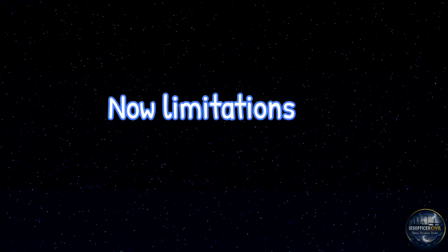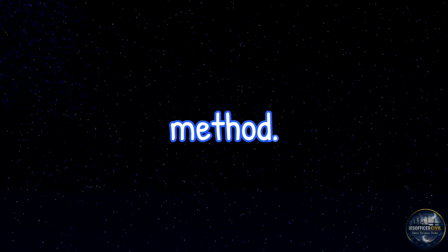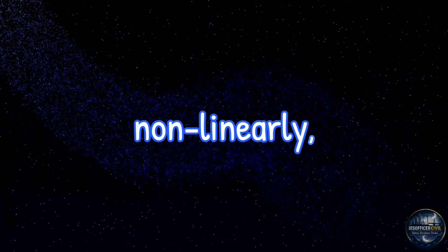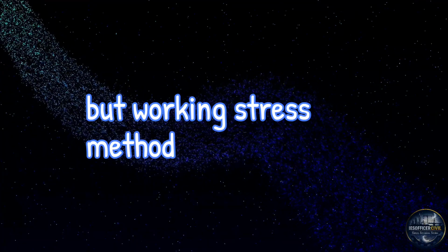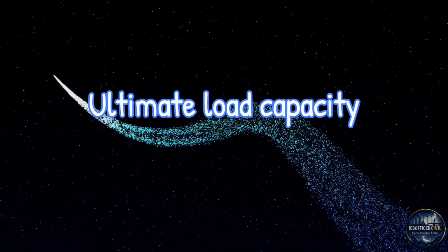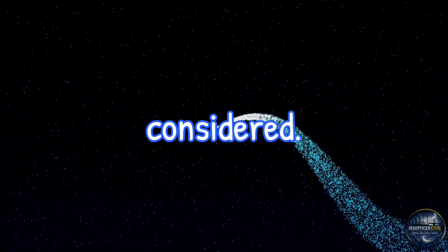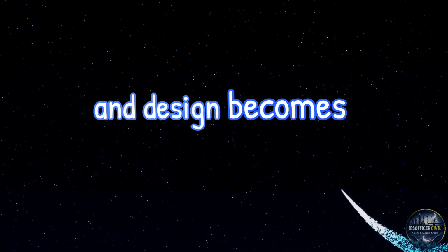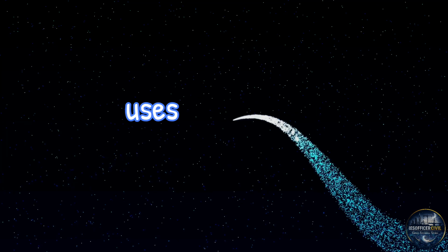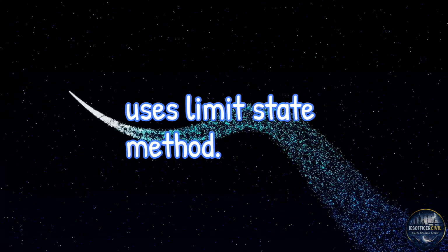Now limitations of working stress method. Concrete actually behaves non-linearly, but working stress method assumes linear elastic behavior. Ultimate load capacity is not directly considered, and design becomes less economical. Therefore, modern RCC design mostly uses limit state method.